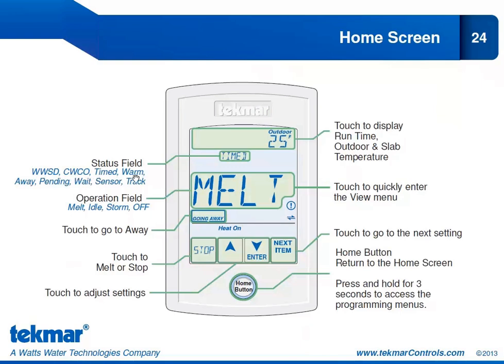Warm, which tells you the slab is currently coming up to melt temperature. Away, if you put it into the away scene. Pending, now this would show if you were in a melt and then the temperature dropped below cold weather cutout, you would see pending on the screen, and it would actually alternate between pending and cold weather cutout to tell you it will return to that melt sequence once the temperature rises above that cold weather cutout.